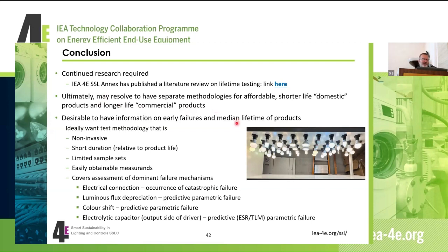So the desirable information to have is on early failures and that median lifetime. Really, that's the critical thing that's important, particularly to consumers. Right, so ideally we want a test methodology that is non-invasive, it's short duration relative to the product life, limited sample sets required, so not a huge amount of testing, and easily obtainable measurands or test results. And it covers the assessment of dominant failure mechanisms that we spoke about earlier.